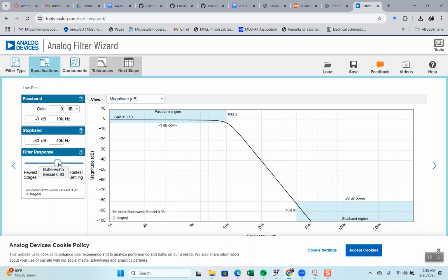Okay. Can you see the word there when I'm wiggling it back and forth? Okay. So over here is something called a Chebyshev filter, right? Which uses the fewest number of op amps. Then it switches to Butterworth, which is the one we're actually using a lot, where the damping coefficient is 0.707. Then there's Butterworth Bessel, which is another kind of filter, and then pure Bessel. And it all has to do with the constants in the denominator. So I'm going to keep it Butterworth, okay?